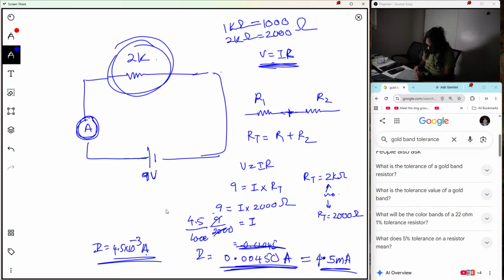Positive, right? Going to supply the current to the circuit, so charges are going to go through the meter. It is like a flow meter. It measures the flow, right? So how many amperes are going through this point. So we have to add the ammeter in series, right? Always in series.